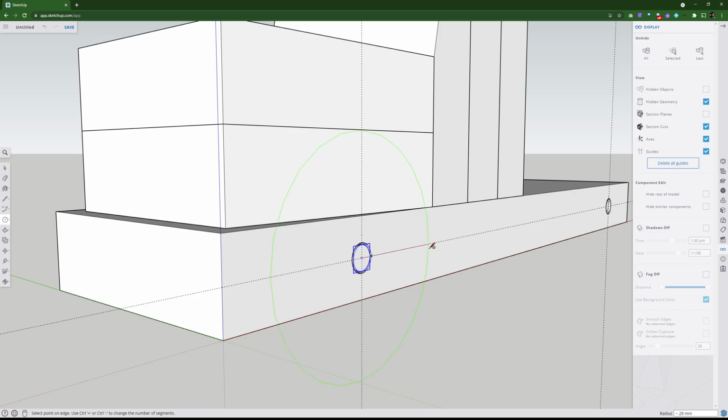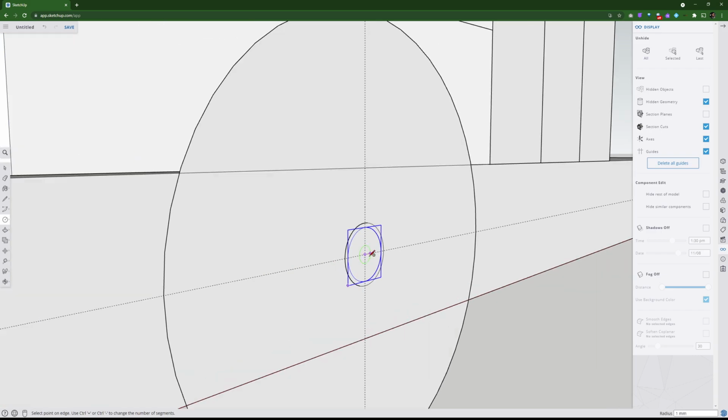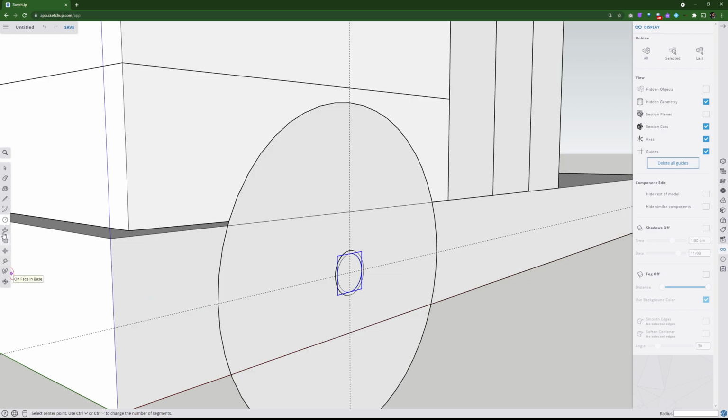It just makes it easier for you if you keep it either on the blue here or the red there. I'm going to make it 26. So I'm typing in 26, hit enter. And once again, I'm going to type in 48S. It's a bit smoother. And I need to do that hole in the middle, which I'll do, it snaps in to there. You can type in 3 mil if you want.